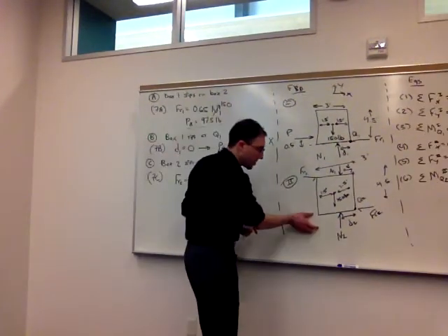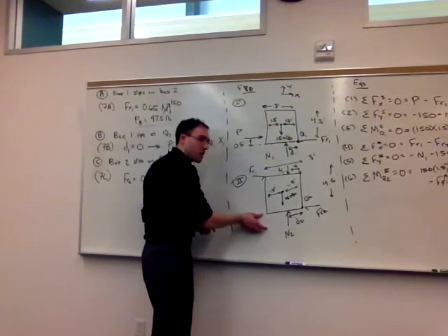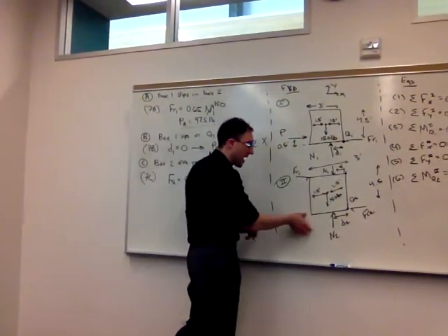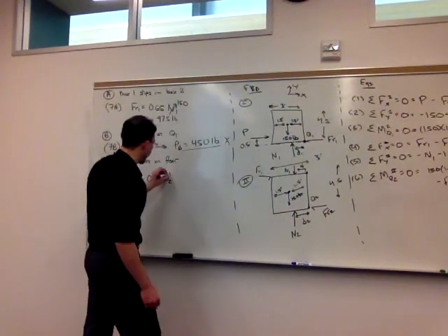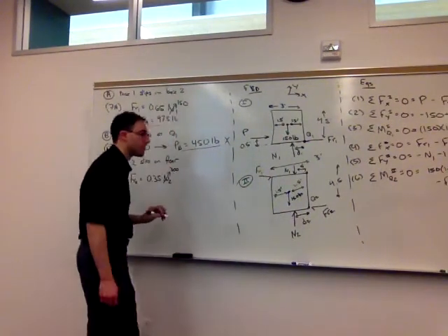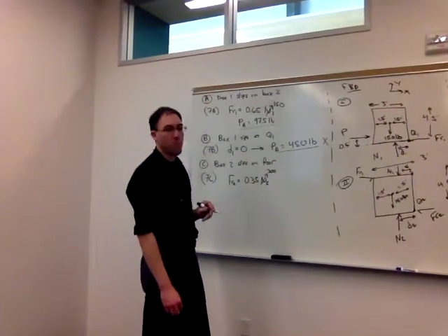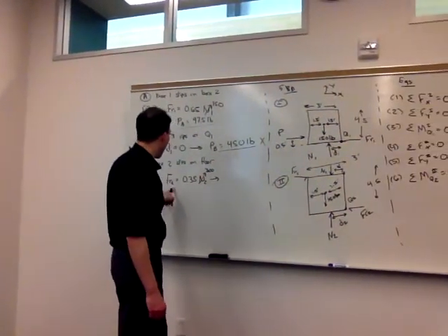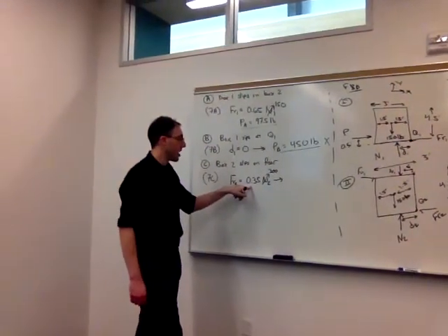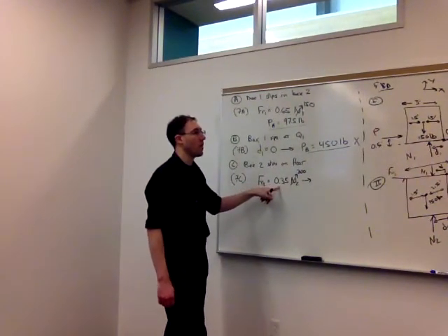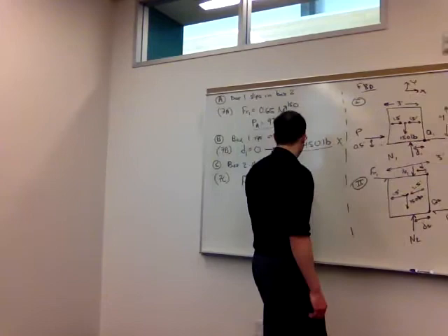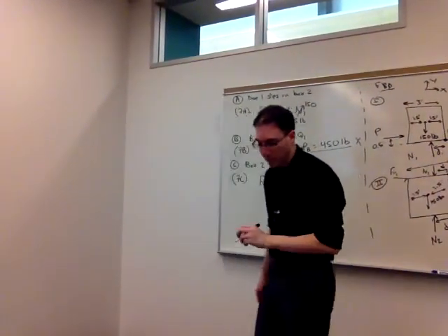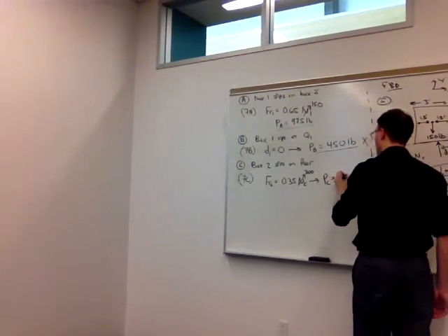It's now these 2 surfaces, so we're using their coefficient of friction, 0.35 or mu s prime, and their contact force, N2, which we know is 300 from equation 5.1. So if FR2 is equal to 0.35 times 300, and from 4.1 we know FR2 is equal to P, that means for condition C, that P to cause this is 105 pounds.